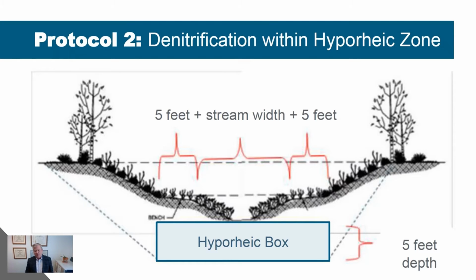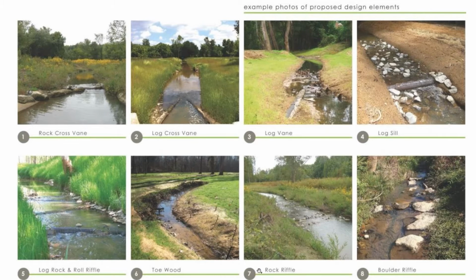So you think of all the streams we've lost in our urban environments, and especially those ephemeral streams, which are more sandy in nature. We've really eliminated miles and miles, hundreds of miles of sand filters across our country as a BMP. So we need to protect this and recognize the value of this zone. So your stream design can really influence this denitrification. Having a lot of bed depth diversity, pools and riffles will help create good mixing zones between groundwater and surface water in perennial systems.